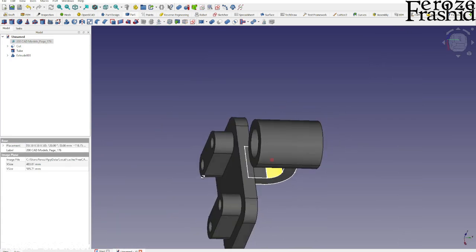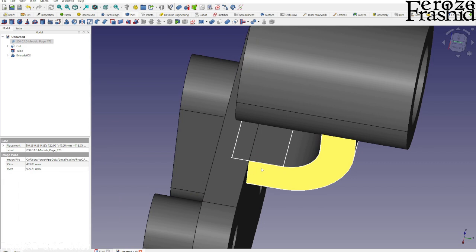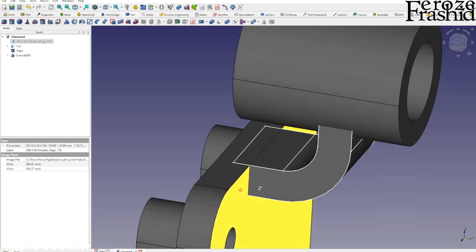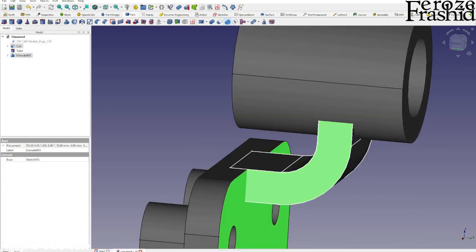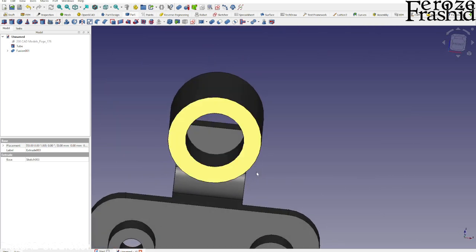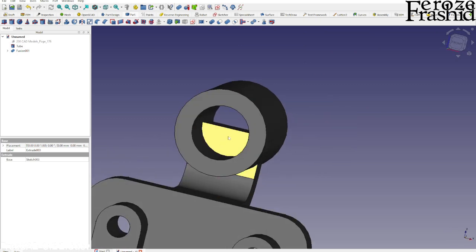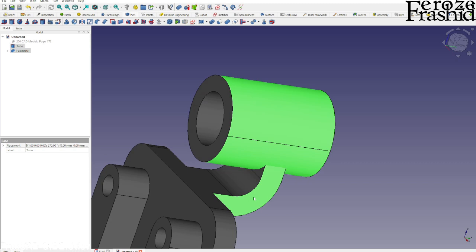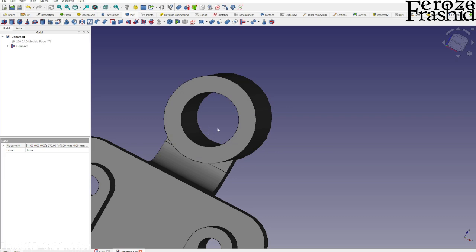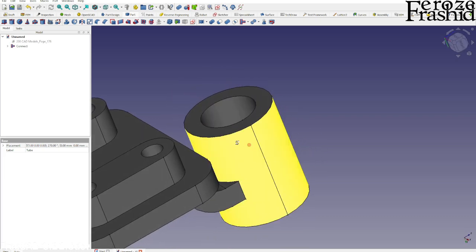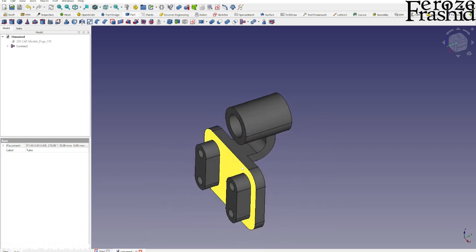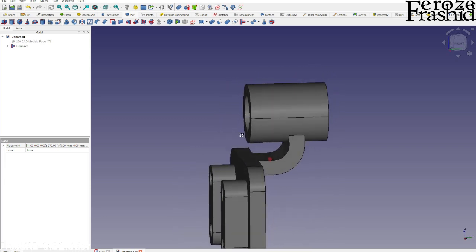So two things. One thing is the body that we just built gets into this previous body, which is not a problem. We can take these two and make a fusion that amends the extra part. Here we cannot make it a fusion. We'll have to cut this part out, right? We can take these two and come here and use the connect object. That actually eats up the inside part and makes a fusion. And you know what? That's our object. Pretty simple, right? That's our object.